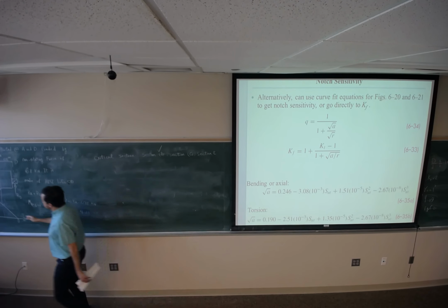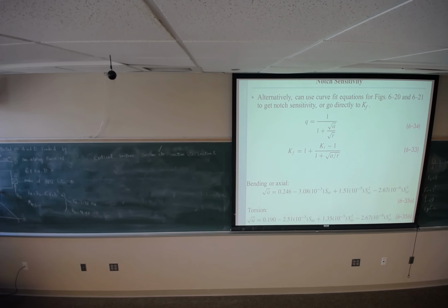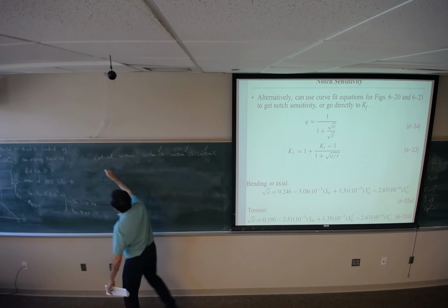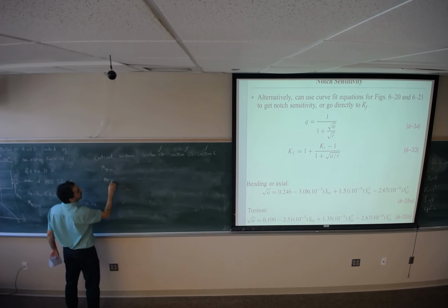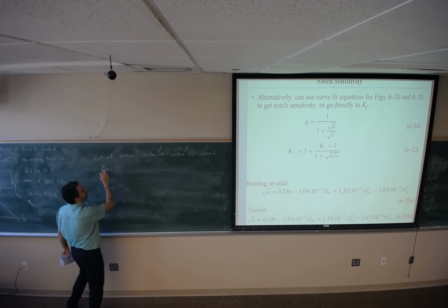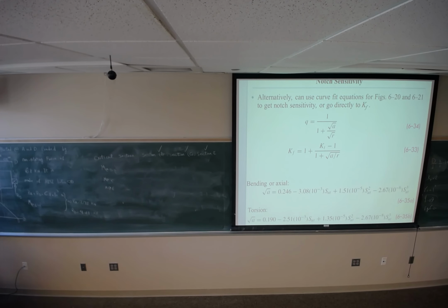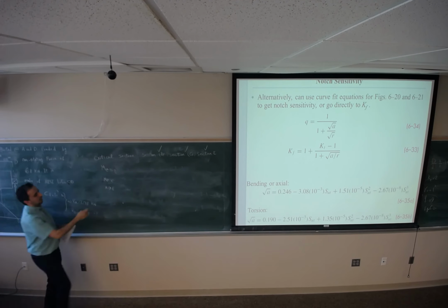And section C also should be studied because we should find the bending moment applied to it, and then see which one is going to develop the greater stress. So I'm going to find the bending moment at these 3 points: M at point B, M at point C, and M at point E. And then by knowing this, I can find the stress at each section and continue the process.